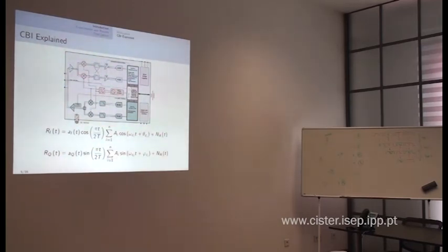Then, of course, they are multiplied in the receiver chain. The first thing is you take the same synthesizer that you used to transmit, and multiply those signals again by the carrier frequency at which you intend to receive. The effect is that it translates these composite signals backward in frequency to baseband.